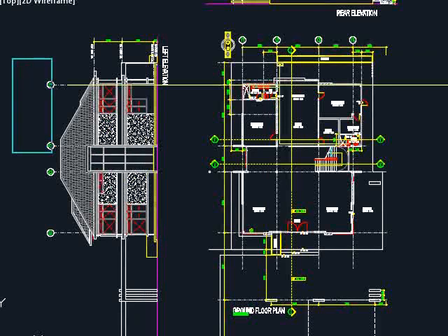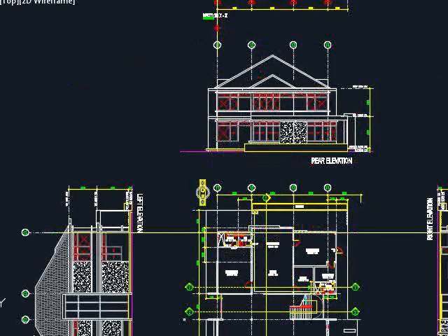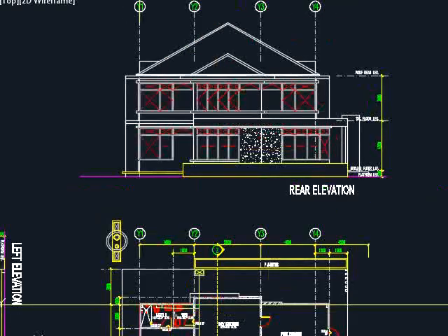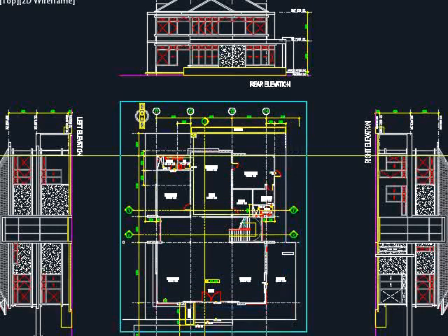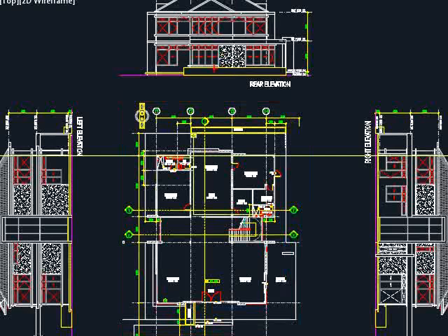You will need to observe the grid line, putting them in the proper positions so that you can make direct alignment in comparisons between the plans. Same goes to the vertical grid line. From there, you can make direct comparisons. Since this one is the ground floor plan, that means you are looking at this plan here. You can check the alignments of the wall with the side of the building on the plan.